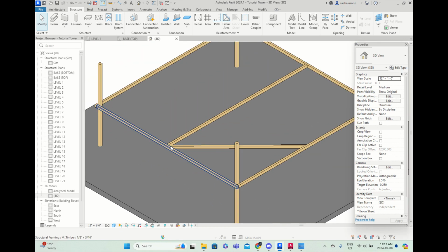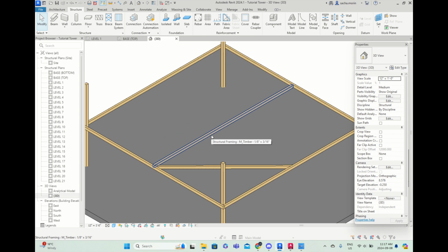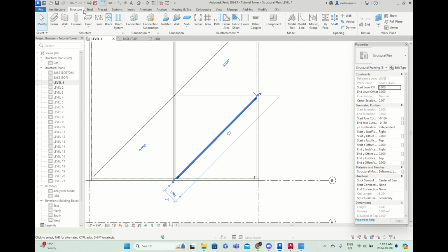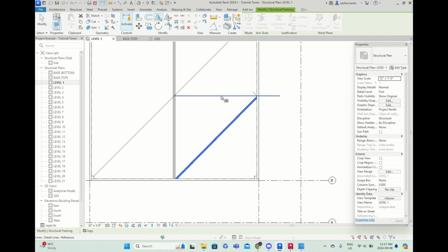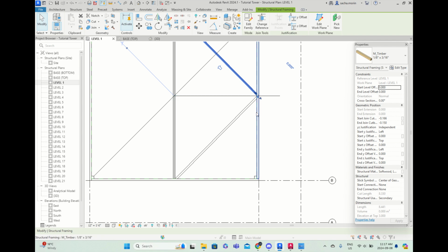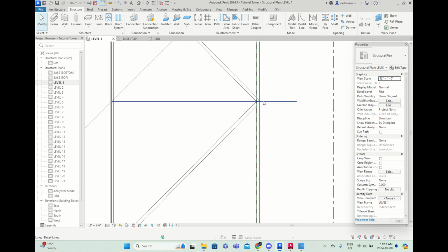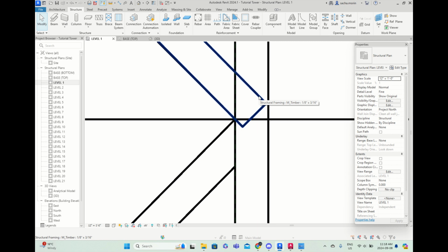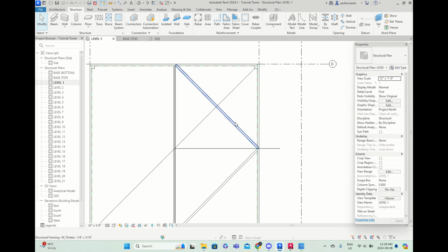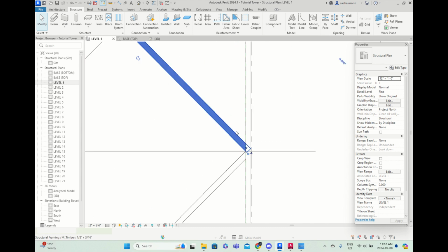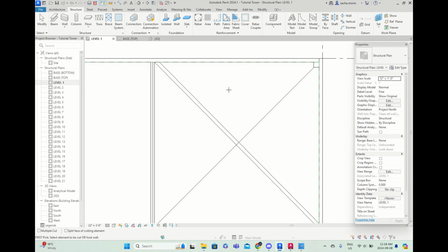It looks beautiful. So now we can go back to doing our tried and true method of using the mirror tool to mirror everything around. So back to level 1, click the beam, mirror on the line. Amazing. Whoa. As you can tell, our cuts didn't transfer, but everything else did very well. So whenever you use the mirroring tool, when you want to mirror beams, it's just a matter of cutting it again. It really does not take that long. Click, click, click, click, you're done.